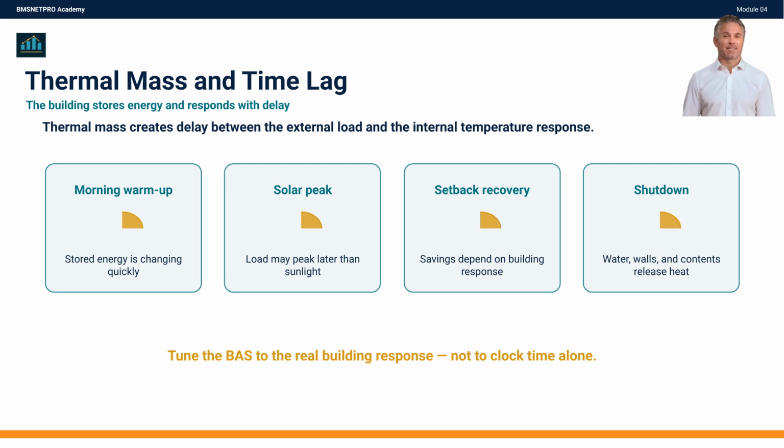The correct practice is to tune the BAS to the actual building response, not to clock time alone. Trends should show how long the building takes to recover, stabilize, and drift.